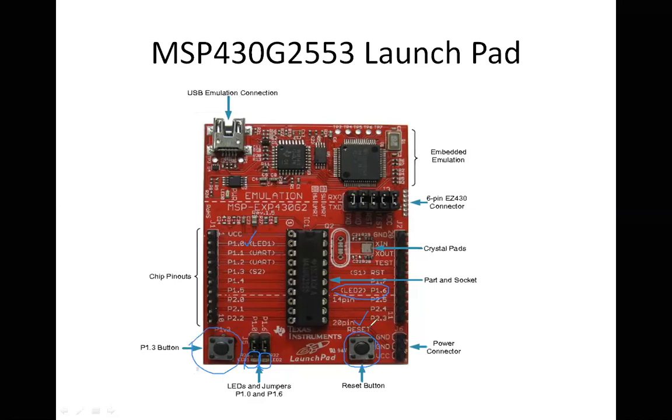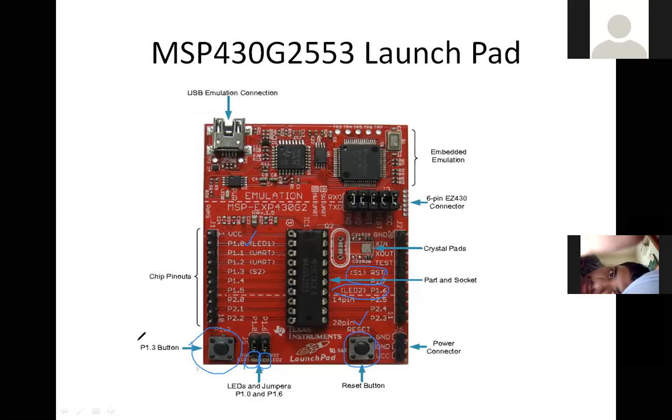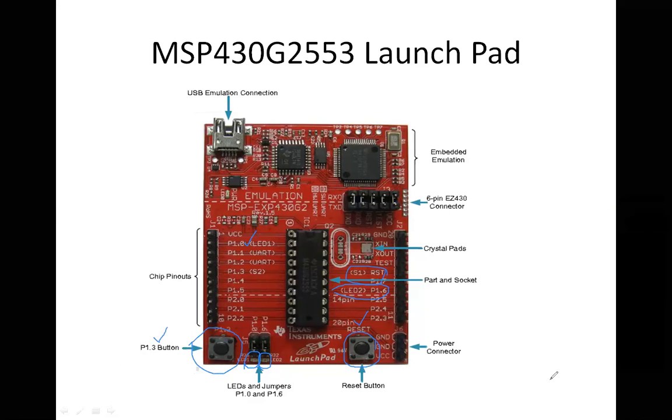This is reset button, hardware reset button, or POR. This causes POR. Let's not use this. This is where a reset button is there. Switch 1 is connected there. Now we want to work with P1.3. So we got LED, we got switch at P1.3. Hope it is clean. Okay, I will stop this screen.